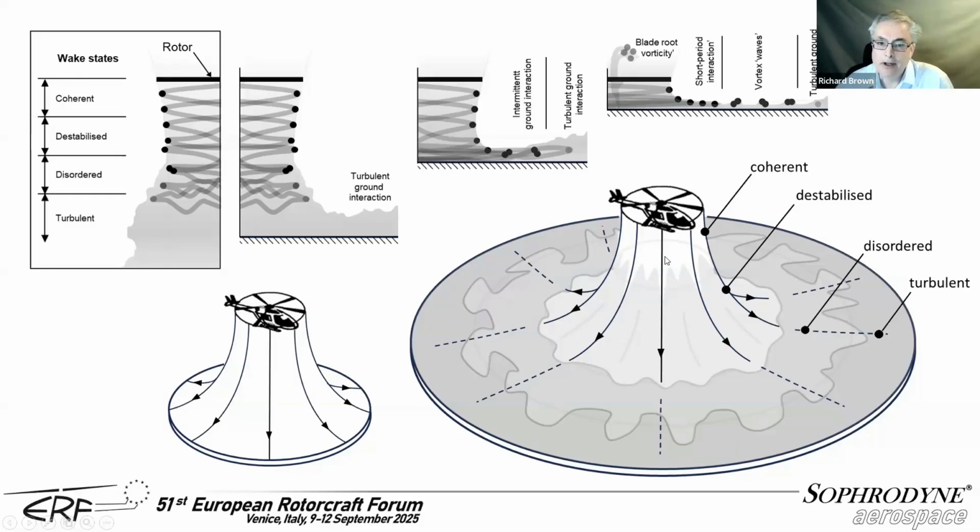So that's the first step in terms of a semi-qualitative, semi-quantitative understanding of what goes on in the wake below a hovering rotor in strong ground effect. In other words, in trying to understand the outwash below a conventional rotor. So we might want to supplant that model over there with something a little bit more complex, where you can see these domains in which the wake out across the ground, or the outwash, might have very different characteristics.